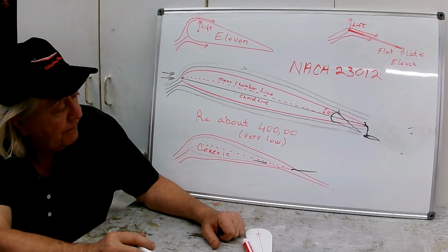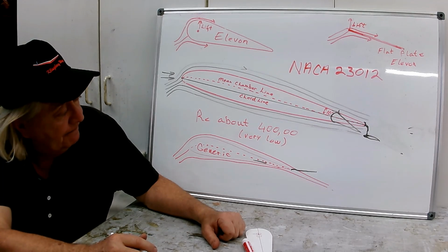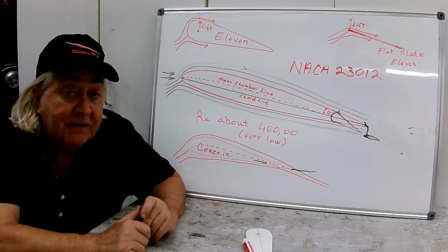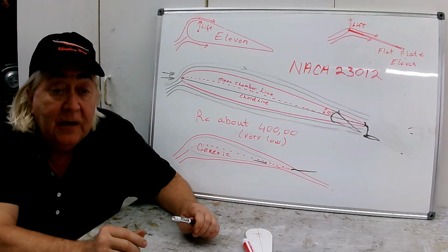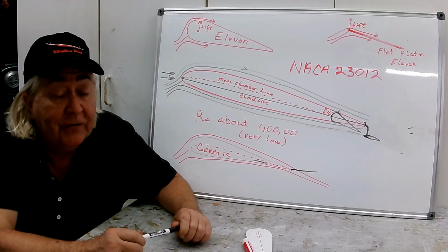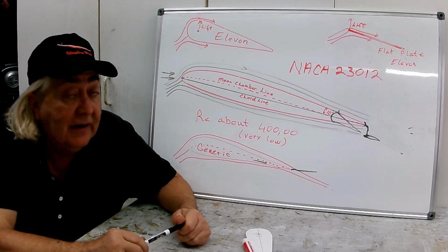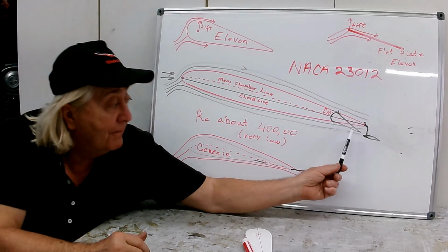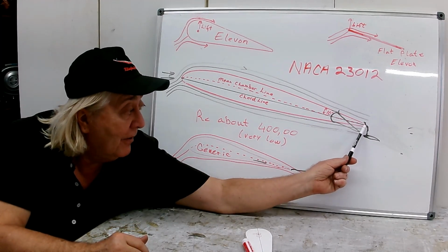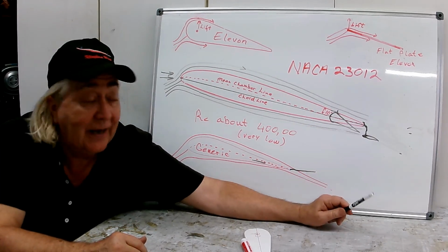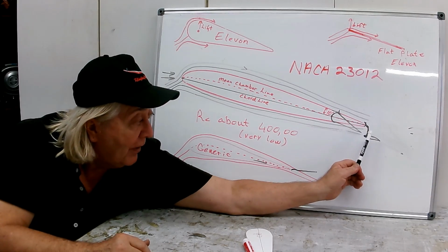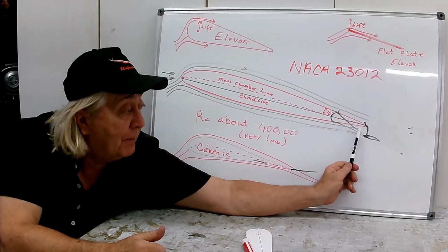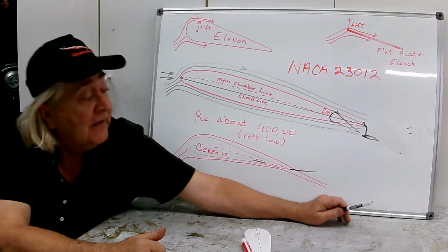Oh, interesting. Well, yeah, that was very effective on the MkII, very effective on all aircraft that it's put on. It's usually used on powered aircraft, and not on gliders. I think it's only been on one glider, that'd be the MkII. This gap here, when you ask the flow to go through this gap, a lot of drag. It accelerates the flow when it goes through this gap, which helps it stay attached to the control surface. Big plus. But you pay a price there with a lot of drag.